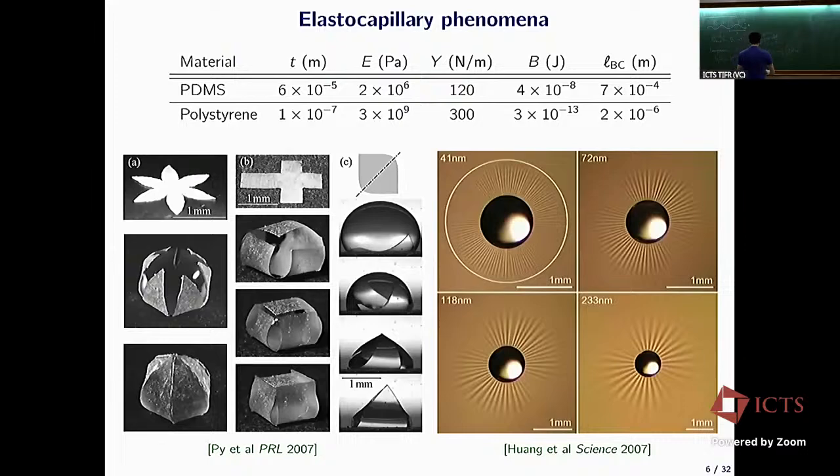So if you put it back in the bending energy, I will write A squared is epsilon lambda squared. So this gives you bending is B epsilon over lambda squared. So if you have only this energy, you want to maximize lambda. And this is why when you do buckling without foundation, like this is Euler buckling, you want to maximize lambda, and you get lambda is equal to L over 2. Okay?